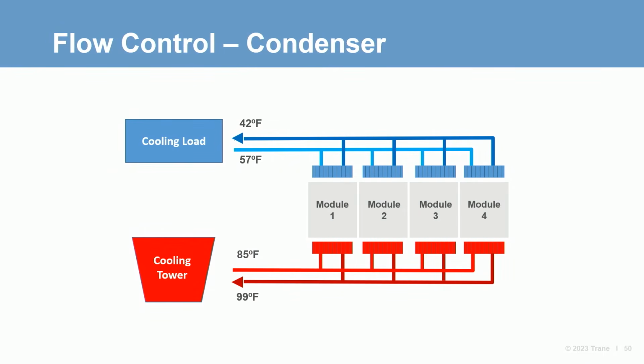We have focused on chilled water so far, but what about the condenser side? Can variable flow be applied here too? The answer is yes, it can. While not as common on the heat rejection or cooling tower side, varying the flow rate can be done and is a bit more simplified. Because there are no valves or loads shutting down on the cooling tower side, we can simply control the pumps to maintain the desired flow at the condenser.